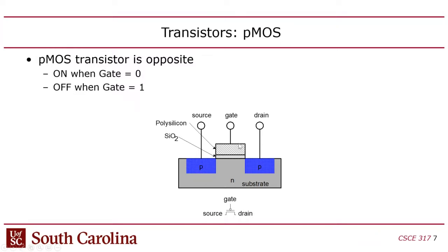So the substrate is at VDD, which means that when you take the gate and start lowering its voltage relative to VDD, what that actually looks like is a negative voltage. What's really happening is that PMOS and nMOS work the same, except that for a PMOS, what turns it on is a negative gate, essentially a negative threshold. There's a threshold voltage that delineates between gate off and gate on, and that voltage is usually about 700 millivolts, 0.7 volts.